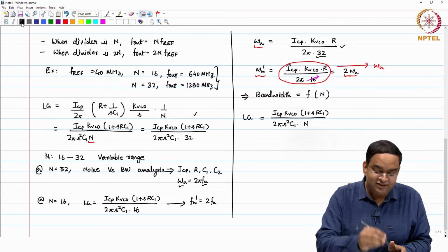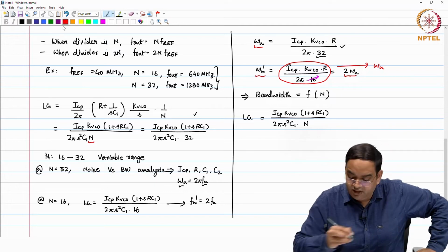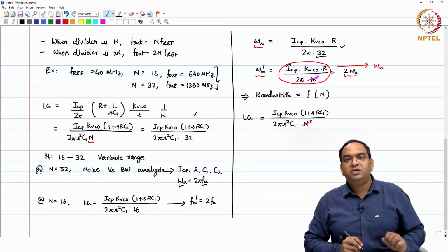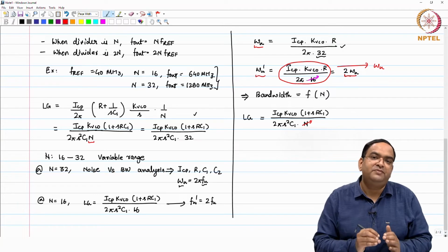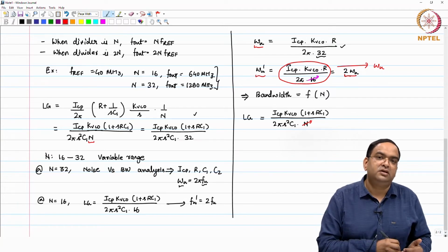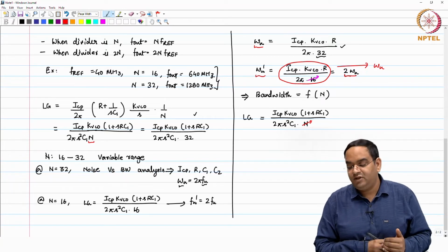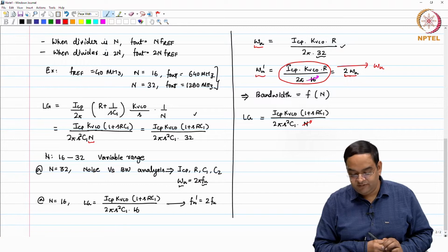If n changes as per the required frequency, I would like to change some other parameter. So, let us say you optimize everything at the highest frequency where you need the minimum jitter, and then you would like to keep the bandwidth fixed, because bandwidth is decided by the reference frequency, and the maximum bandwidth you cannot increase more than a certain value.